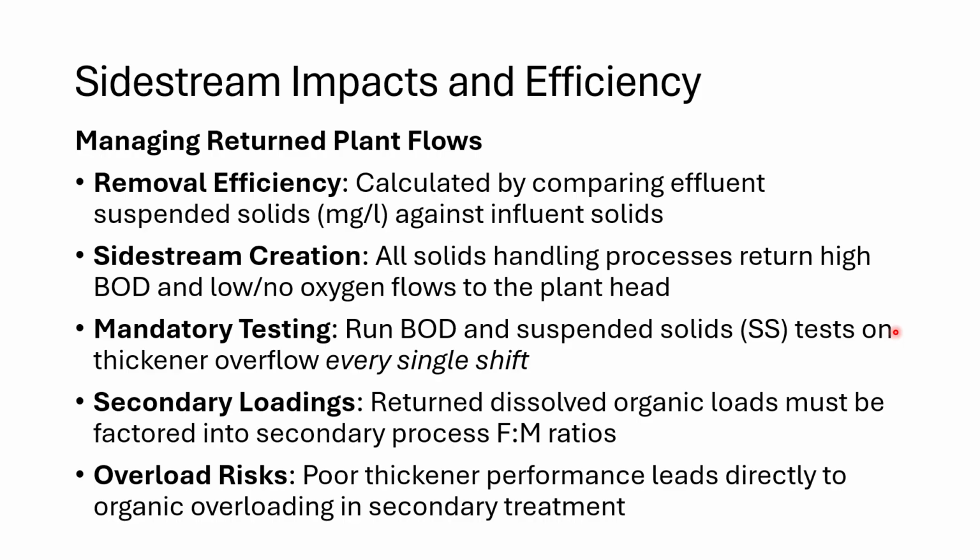So in this process, the superintendent's going to have you guys take some samples and run them to the lab. You're going to run BODs during this process, as well as suspended solids on thickener overflow. So if there's any water or wastewater that overflows the thickener, that's going to be tested every single shift, every 8 hours. You're going to run a BOD and run a suspended solids test.